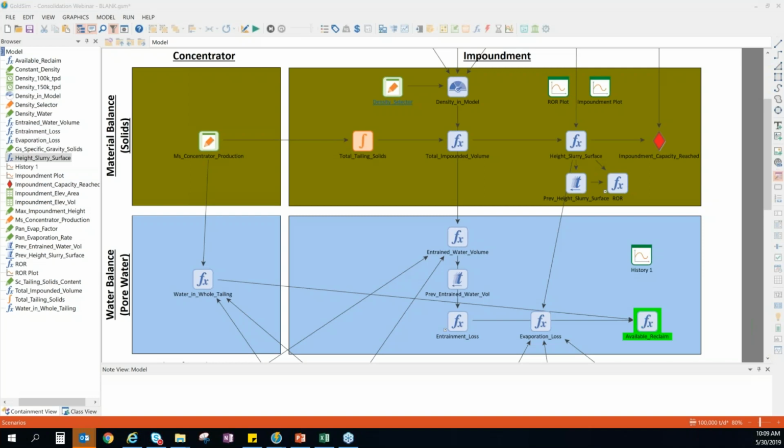Now, in any mining operation, the ore has the ability to change with time, just as new geologic units are encountered in the pit or in the underground operations. So changes in those material properties could lead to changes in actual consolidation behavior of your impoundment. The other thing is, some of your deposition could lead to segregation. And so the segregated material might have different properties. So certain aspects of your impoundment might consolidate at different rates than others, even though when you did your modeling with Condis, let's say, you assumed it was all one homogeneous material.